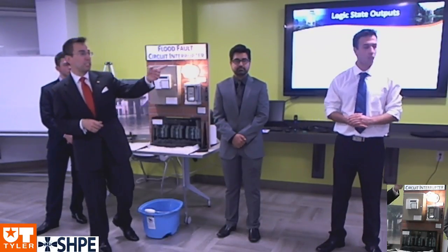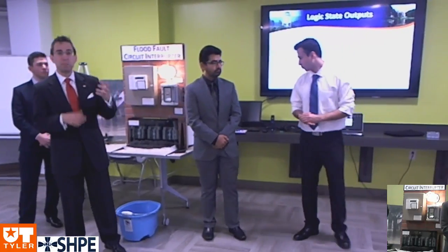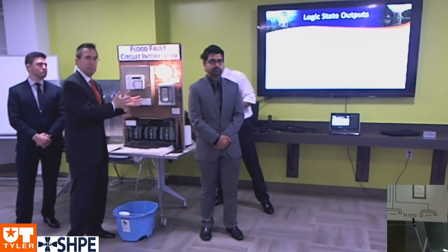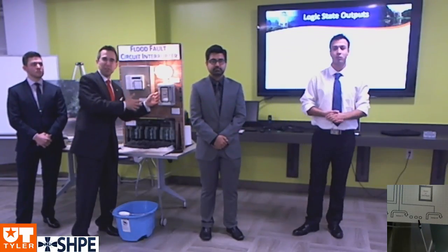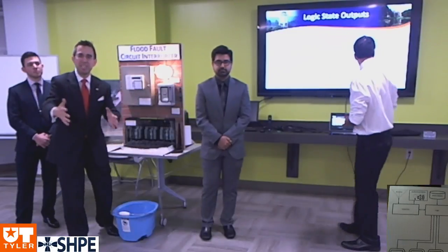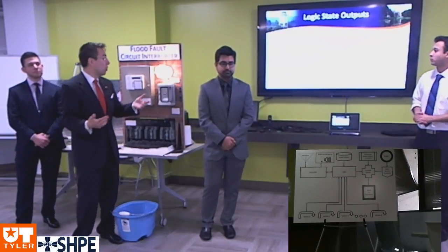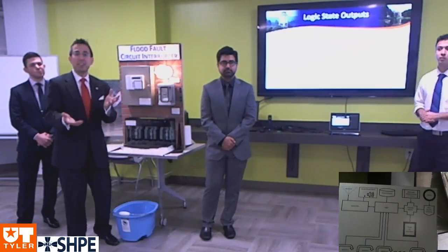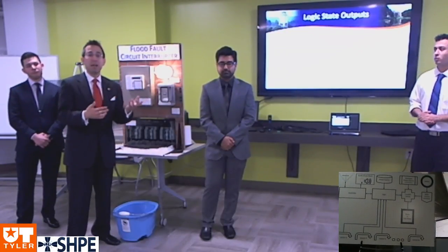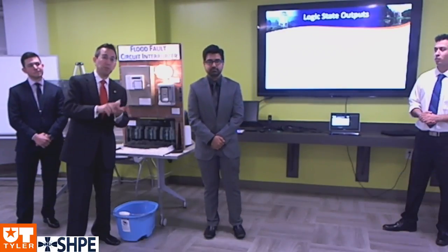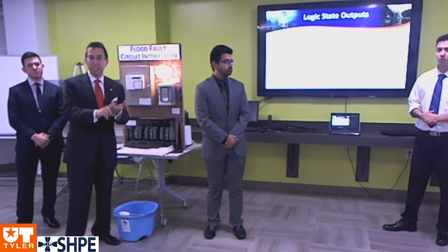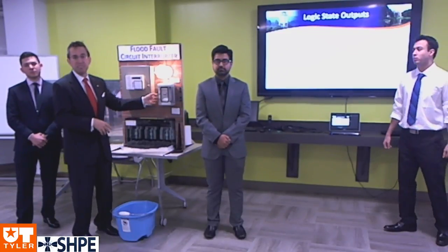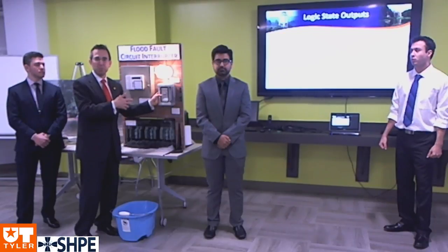If you look back to our original design here, we talk about how we can integrate with a panel or sub-panel. One option, and that's what you're seeing up here, is that we're only taking one circuit offline, so maybe the downstairs outlets. But there's really no reason why this same system couldn't be integrated with the main circuit breaker and take the entire location off. In part, that's all about the design balance for whether you want convenience or safety. Both options are really available in this. We're just demonstrating a single branch circuit, I think, to answer one of your questions.